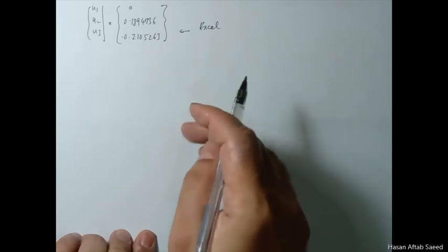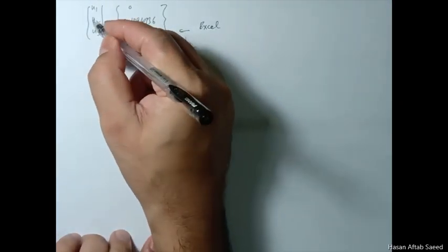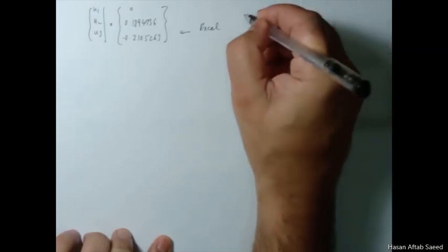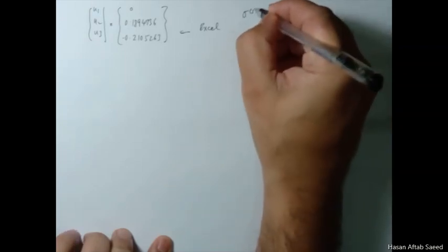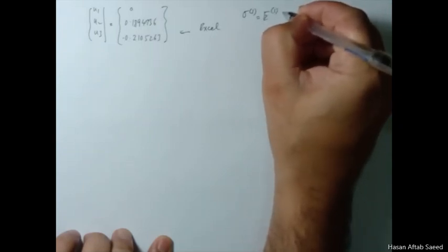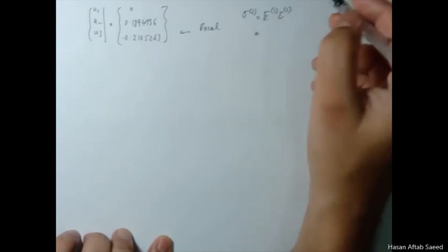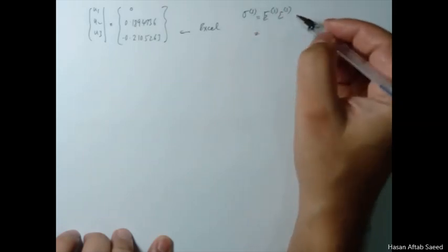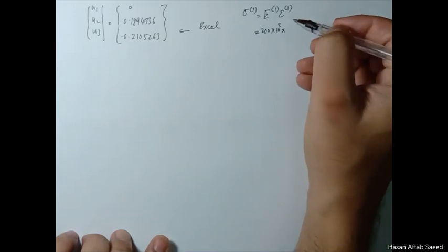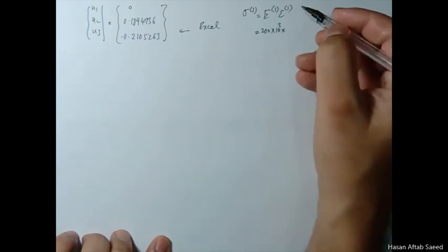Now, the next step after calculation of displacements is strains and then stresses. If we do the two steps in one go, this is how it would look like. For element 1, you have the Young's modulus 200 GPa converted to MPa here.